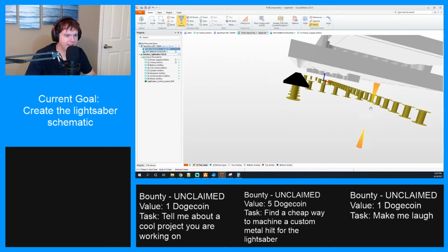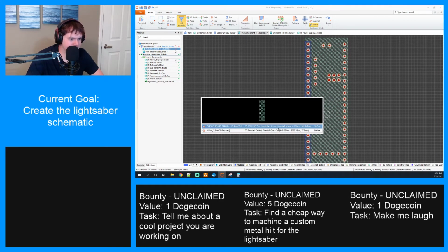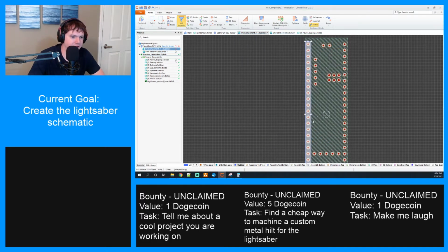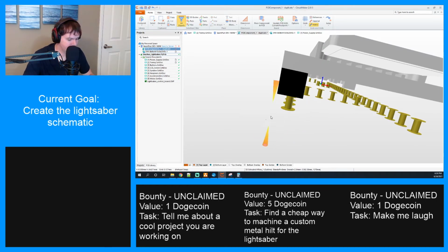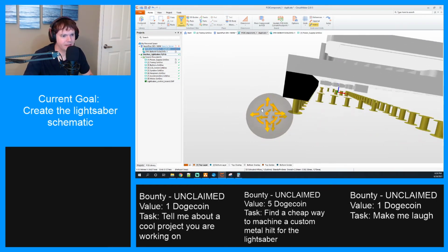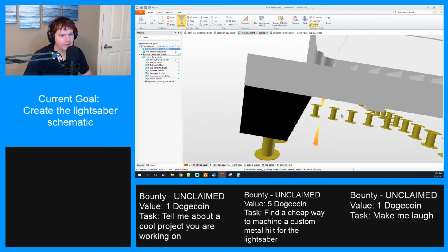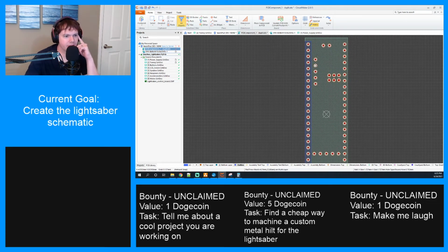That doesn't feel right. Hold on. That looks really small, actually. It should be 2.54. It was way too small. All right. Now let's check it out. Oh, that's perfect, actually. So yeah, the Teensy's the correct height off the board. Perfect. All right, so we just need to run through and do that for all of these different sections. And then we'll have our Teensy model finished.